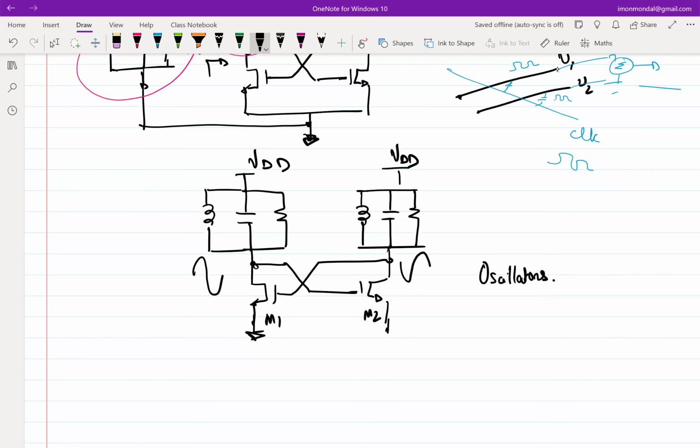Sure. But everything that you said doesn't answer my question. That is the negative resistance, agreed. Where is the energy coming from? Yeah, somebody said VDD. Yeah, obviously, if you don't find anything, everything comes from VDD, right? That's the source. You take away VDD, nothing is going to oscillate. So ultimately the energy is coming through the negative resistance, and where is the negative resistance getting the energy? It's coming from VDD ultimately. Right? Okay, fine.